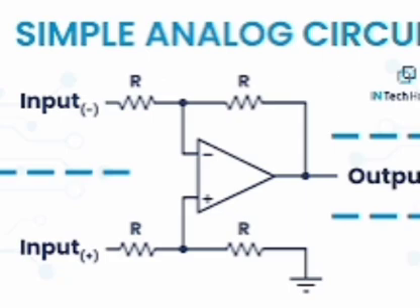Coupling capacitor CC: lower cutoff frequency FL equal to 1 by 2 pi CC into (RC plus RL). Bypass capacitor: lower cutoff frequency FL equal to GM by 2 pi CE. Blocking capacitor CB: lower cutoff frequency FL equal to 1 by 2 pi CB into (RS plus RI). Pi model or high frequency model.